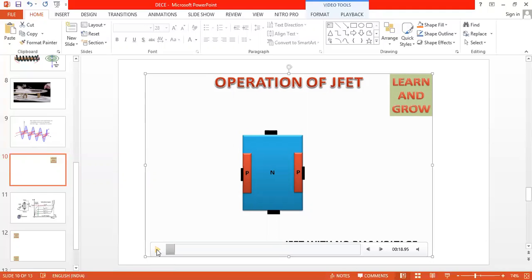So we have the junction field effect transistor, which can be of p-type and n-type. We are going for the n-channel junction FET. Everywhere, every company, every electronic device is using n-channel extrinsic semiconductor, because the speed of movement of electrons is fast when compared with the speed of movement of holes. So p-channel material we are not using for the practical approach. If I want to design a new smartphone also, I have to take an n-type silicon chip.